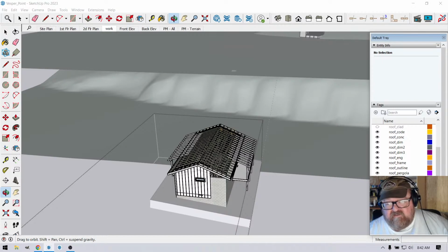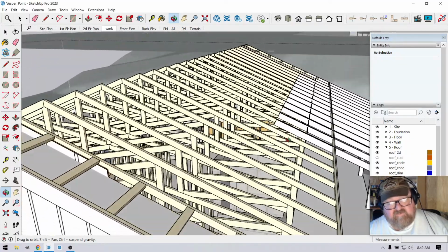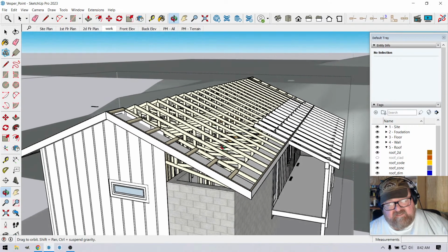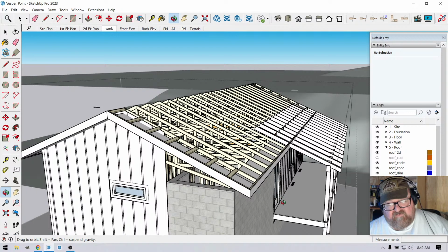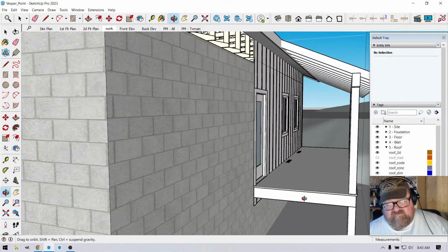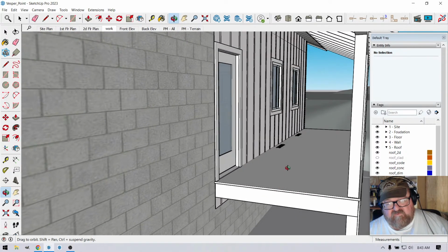Okay, that's what artisans do. If you want to be an artisan, stuff that's on a roof or on a floor is decking, and if it's vertical, it's sheathing, wall sheathing, roof decking. Now when you get into floors, floor decking is the subfloor, but flooring is the finished floor. So this porch floor will have porch flooring.